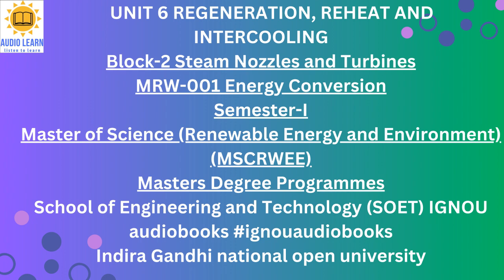6.1 Introduction. The fundamental forms of energy with which thermal power plants are primarily concerned are heat and work. Heat gets converted into work. In a heat cycle, the working medium receives heat at a given temperature from a heat source, converts part of it into work and discards the remainder to the receiver. The next cycle then follows.